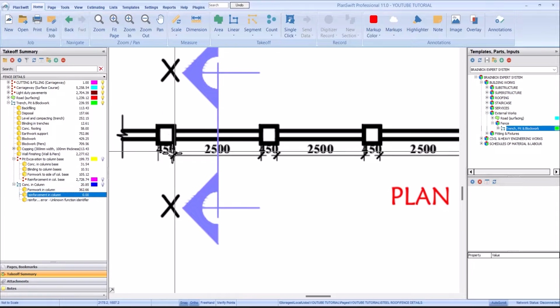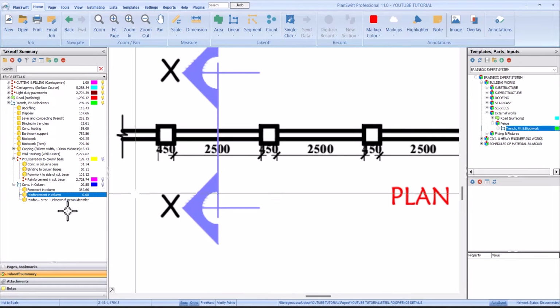Since I only have piers here, there's no need for me to put in figures for the concrete in column, the pit excavation, column bases and the rest. So all I need is just my details for the piers and the rest. I'm just measuring this so that in case your plan came with only the wall and columns without piers, you should be able to measure it.